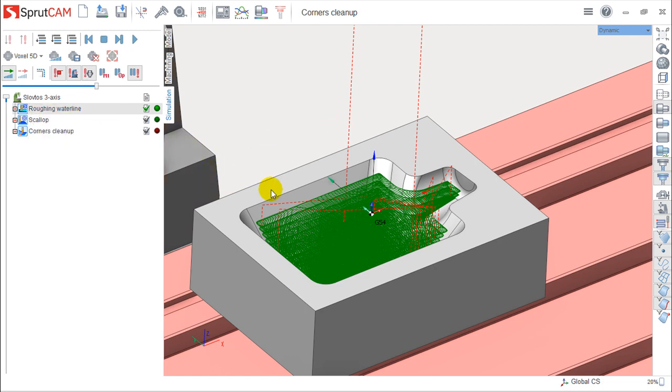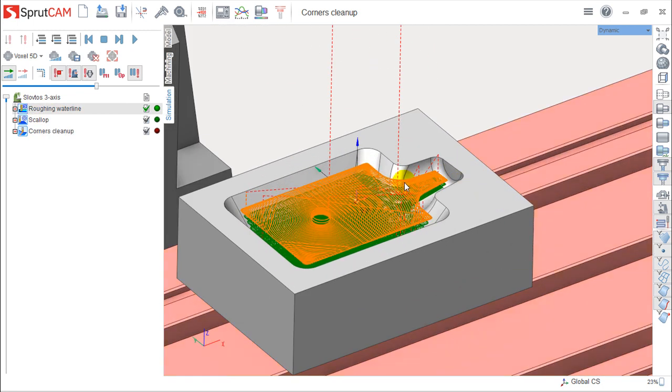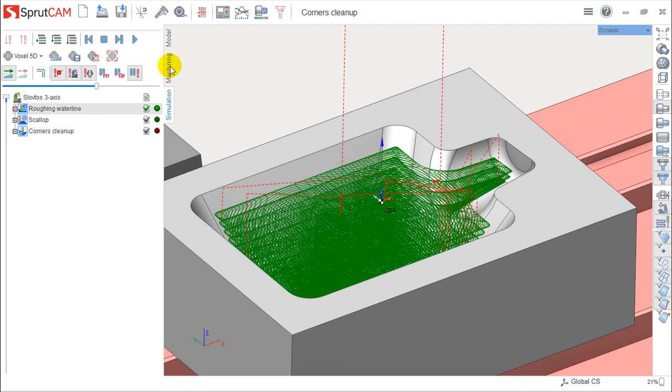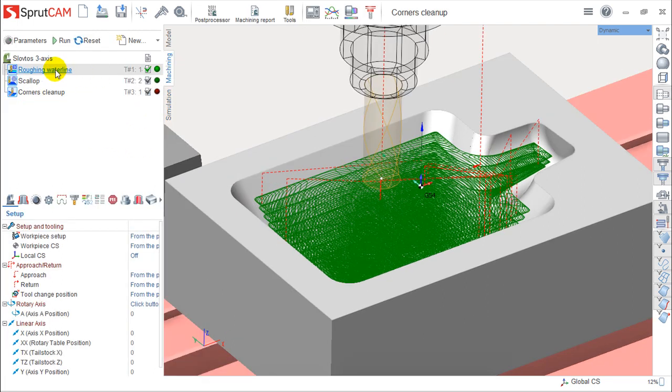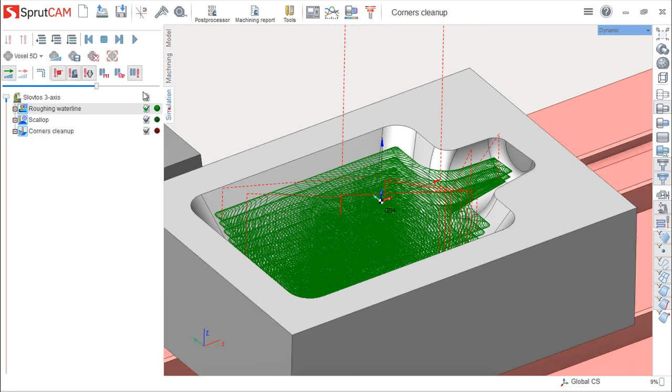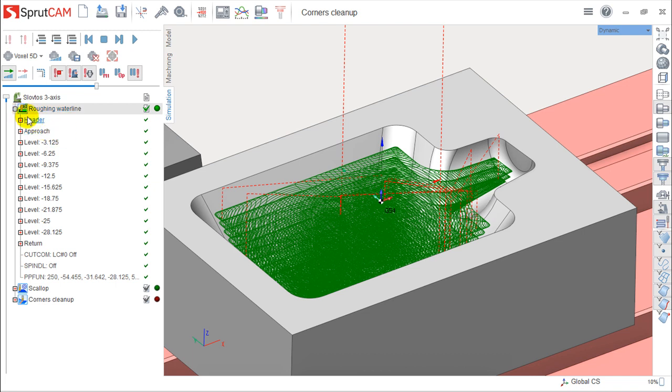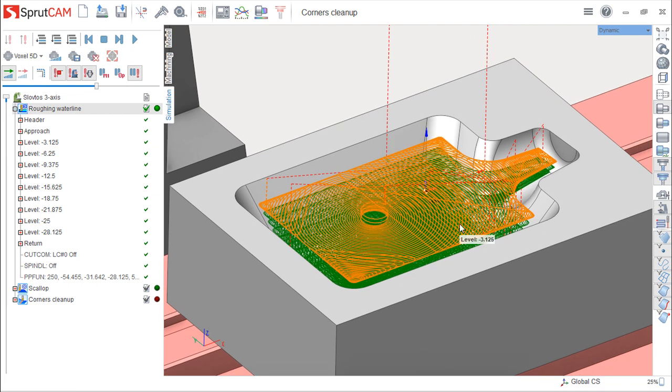But in this particular video, I would like to show you first the structure of the toolpath. What we get under machining, in this particular case, is three programs. We can open these programs, as you can see, and we have what we call the CL data of the calculated toolpath. This CL data has different commands, and we have a list which you can see on the theoretical side of the course.